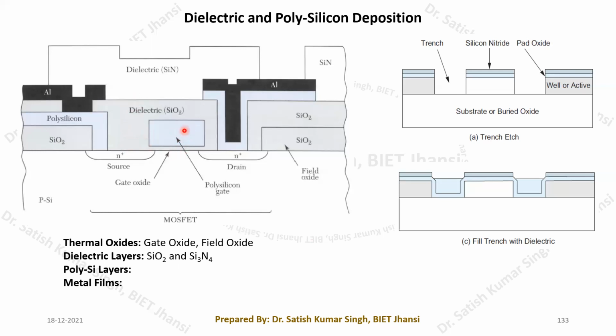Then you can find another SiO2 layer that we have. And here this is our polysilicon layer, which is making a contact with this particular N plus source. And again, here you can see another SiO2 layer that we have grown, and here again we have this polysilicon layer. After this polysilicon layer, we have deposited aluminum and then we have made the contact to the outside world.